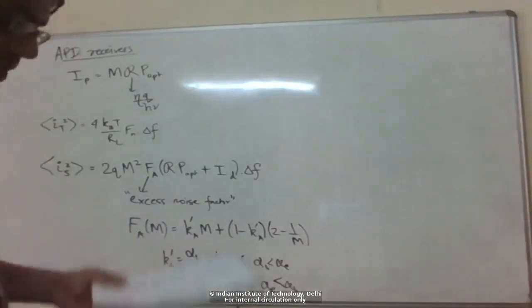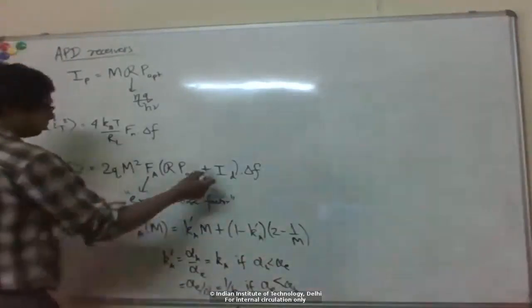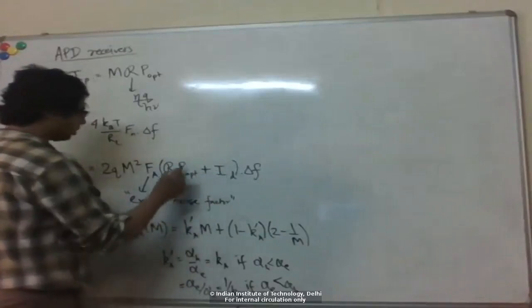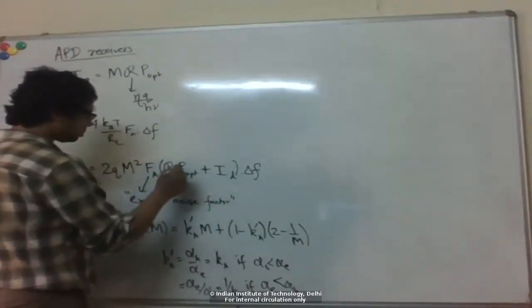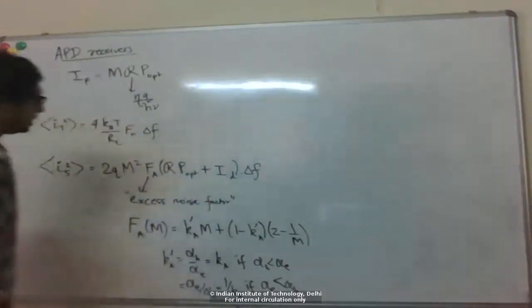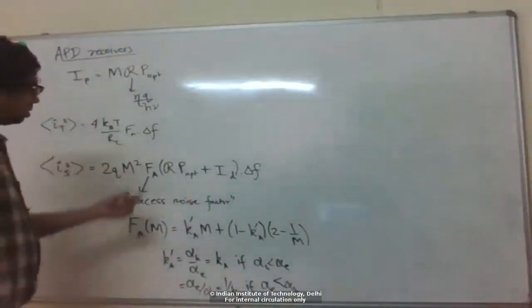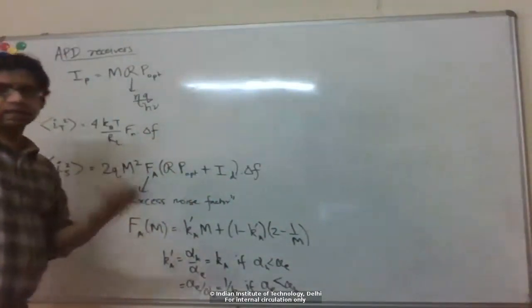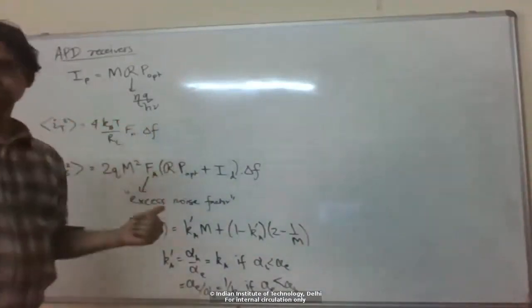Can we justify why we are not neglecting dark current? In most cases, we would still neglect dark current here if the optical powers are reasonable enough, but we just keep it because, for the APD, what you're saying is right. M is large, so that means we could be in the shot noise limit for lower optical powers.